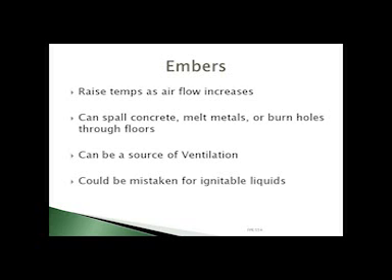And embers themselves, not just the heat related, but sitting on concrete next to metals, they can spall concrete on their own, they can melt metals, and they can burn holes through floors. It can be a source of ventilation if they burn a hole through a floor, if they spall concrete enough, or melt through the metal.